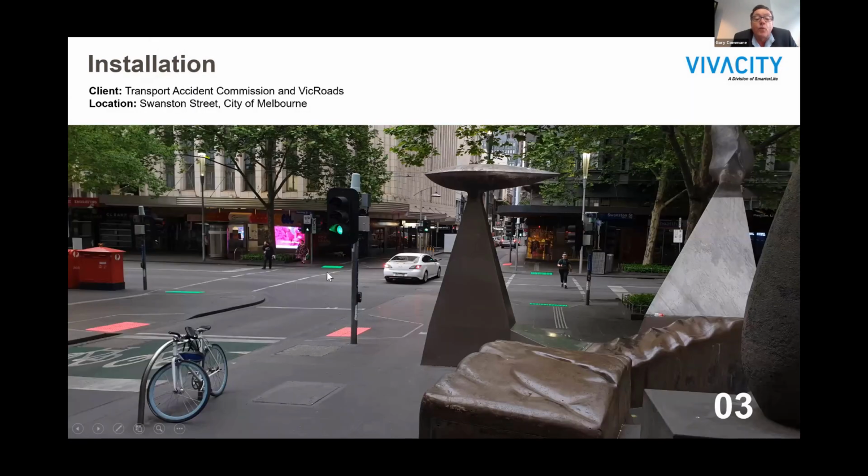What we've done here is that when we supply the tactiles, we also supply this device here, which is the control box, which you can see is fitted onto every pole at every section of the crossing. Inside this control box, we have what we call ambient sensors that pick up when light drops, so it will dim the tactiles accordingly. So at dusk, these lights will dim down to about 70%. It drops by 70% of the daytime brightness level. This is all controllable, but this is the brightness level that was determined and decided by DOT at this installation.